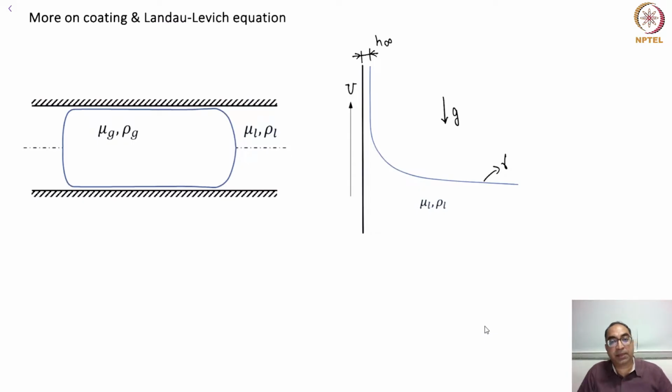So in this lecture, I want to continue the discussion on coating and derive a very classical equation in fluid mechanics called the Landau-Levich equation. Now, I'm showing you two figures. They appear very different problems, but hopefully I'll convince you that these two problems are intrinsically related.